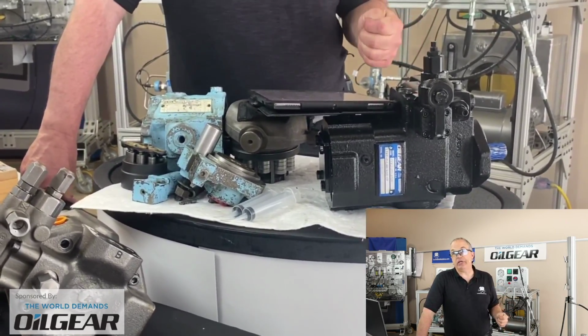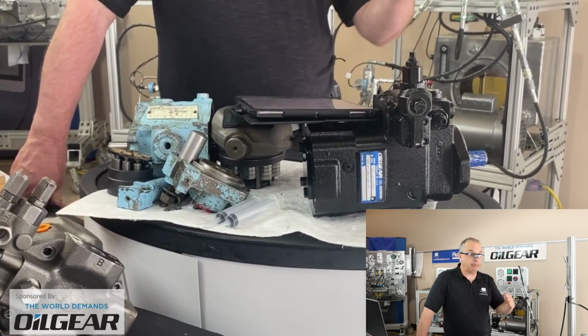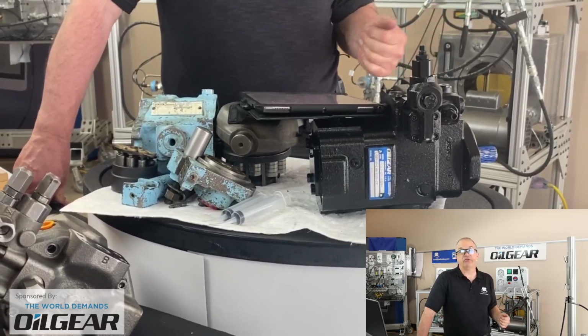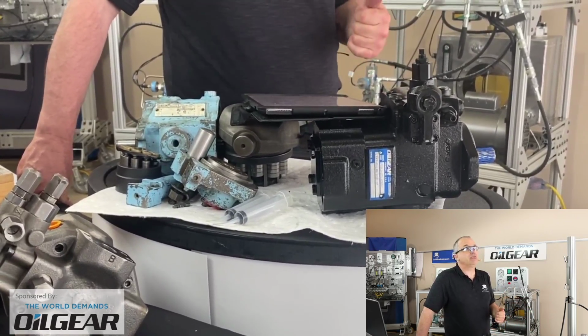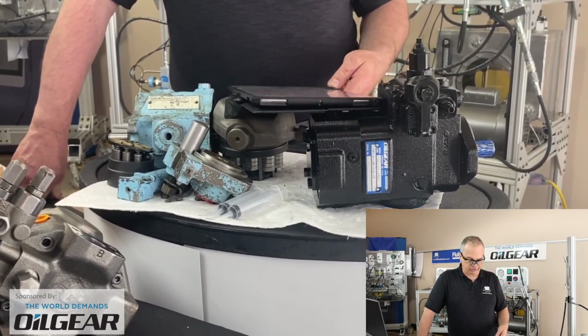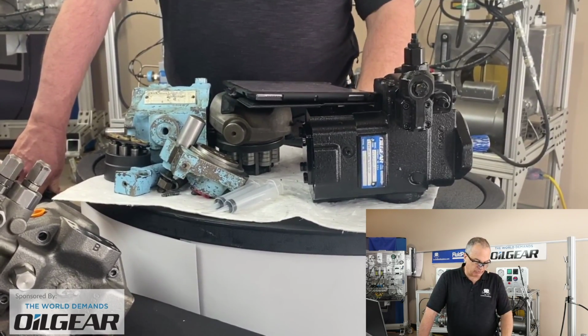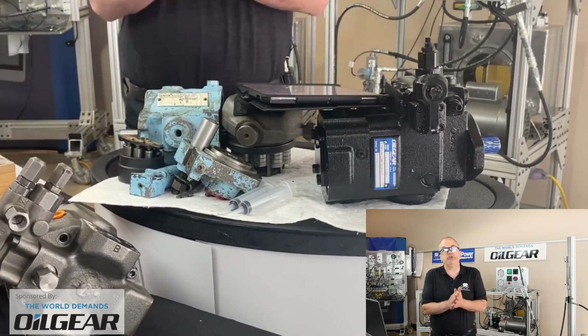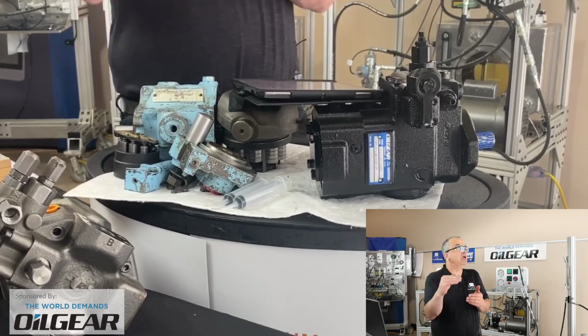What I like to see the case drain flow meter tell me is that the pump has gone off stroke when it's at a certain level, and some other things like that. But leaving it there permanently can cause some problems as well, unless you know how much resistance that case drain flow meter offers against case drain flow, which should be kept very minimal.